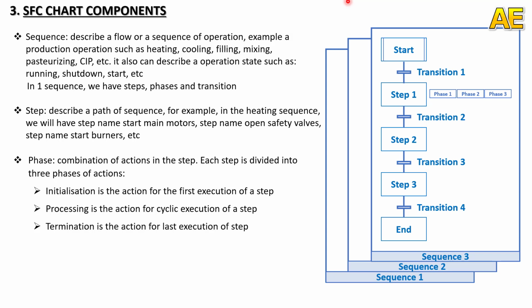A step becomes active after the preceding transition passes control to it. The actions are triggered and executed. A step becomes inactive after the successor transition is satisfied.